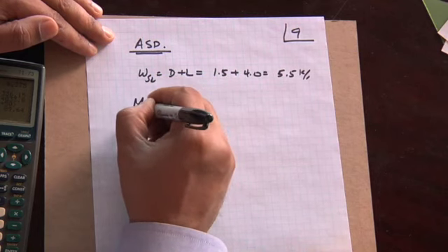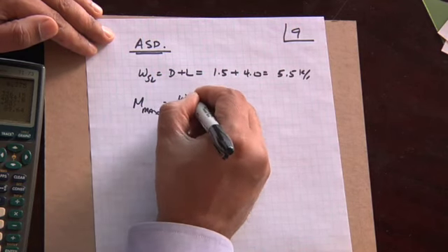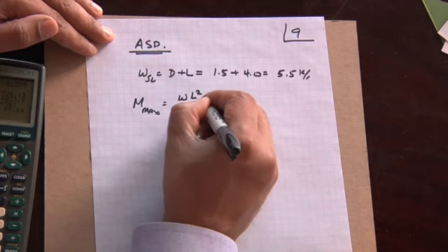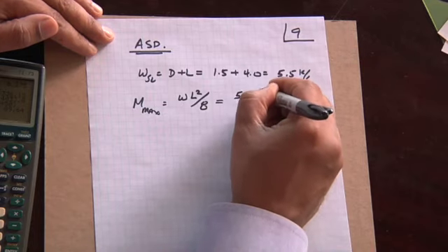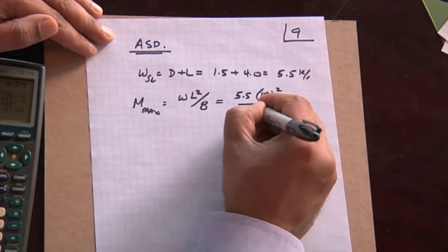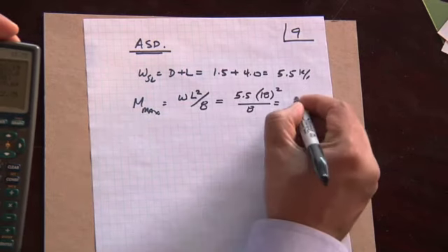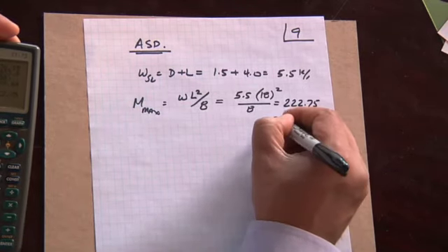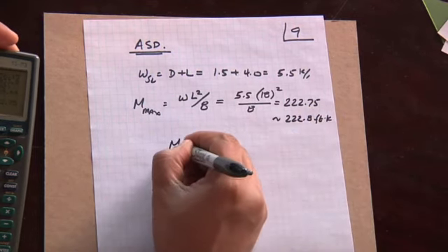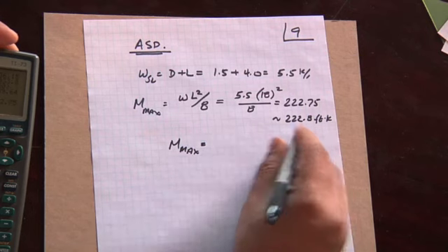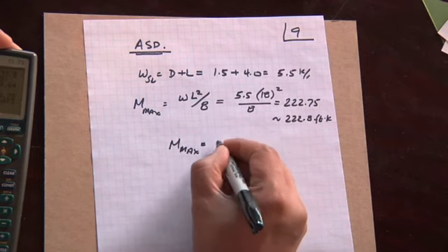We calculate the maximum service moment, same equation, WL squared over 8, except that now we're using the unfactored loads. So that's 5.5 times 18 squared over 8. Let's see what that comes out to be. 5.5 times 18 squared divided by 8 is 222.75, we'll approximate that to 222.8 foot-kips. We have to convert the units, so we multiply by 12. We get 2673